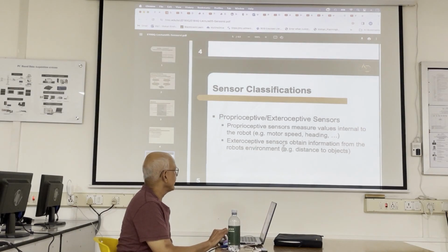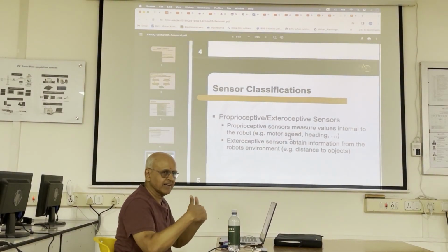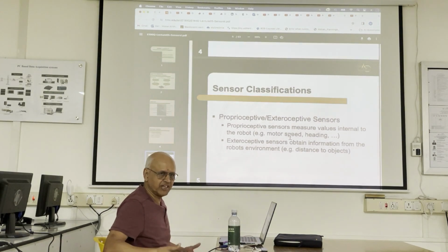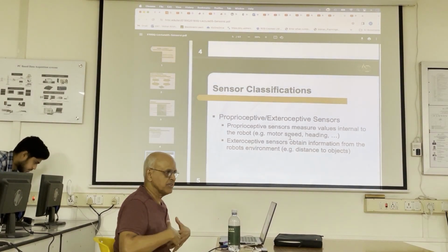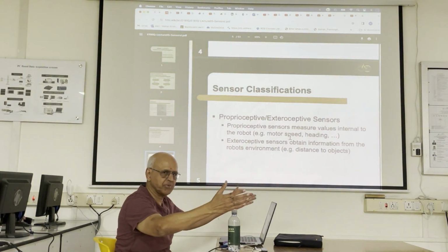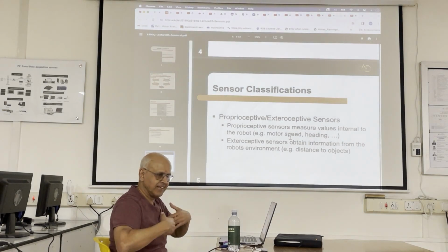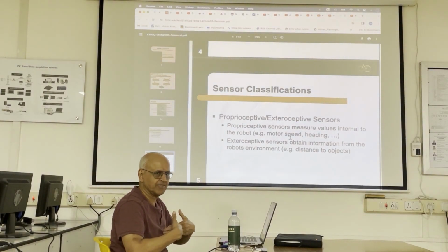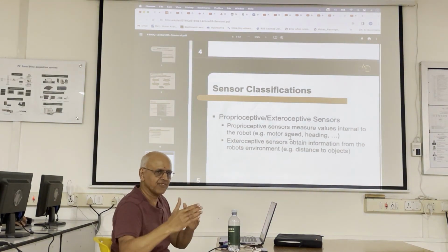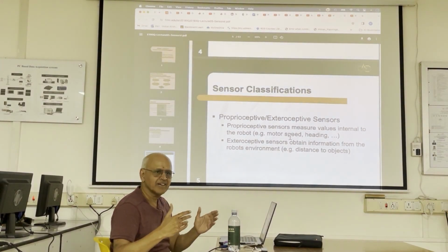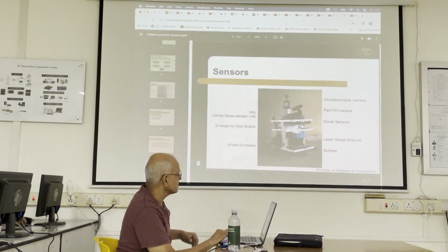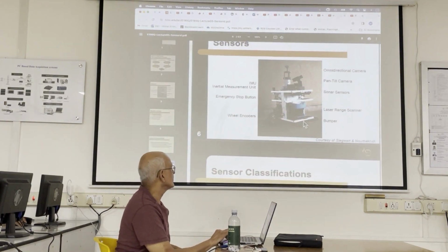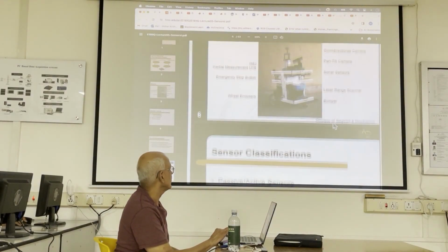No. Odometry is looking at yourself. When you're measuring wheel odometry or your velocity, it's all measurements of the robot. Measurement of the surroundings is done by exteroceptive sensors. Measurement of oneself, like counting steps, is proprioceptive. If you look around, remember the second part of Kalman filtering, you look up, that's extero. You point a camera or LiDAR or something else. So that's all it is. Look at them again and point out which are the exteroceptive and which are the proprioceptive.